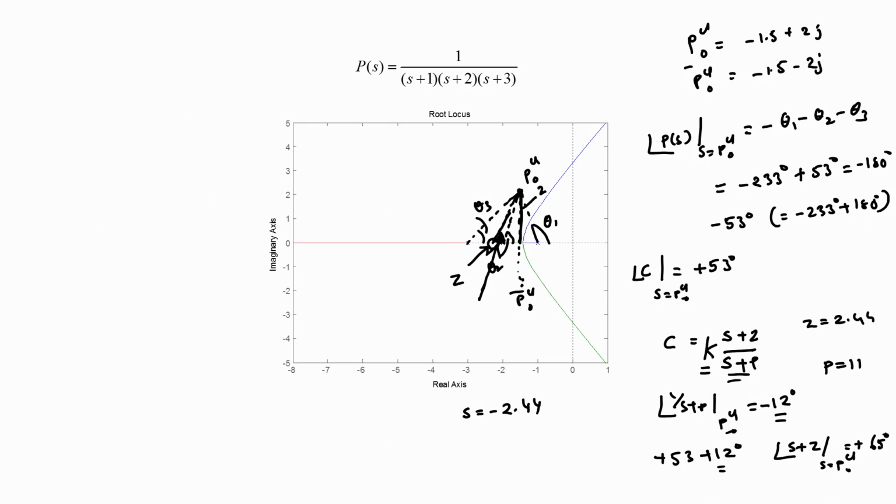What we need to do is to apply the condition for root locus. So, if a point P_CL0 is a point on the root locus, then 1 plus K times C times P, where C is the controller transfer function, P is the plant transfer function, evaluated at the point s equal to P_CL0 should be equal to 0. This by definition is valid for all points on the root locus, and therefore is also going to be valid for point P_CL0, because it is now a point on the root locus.